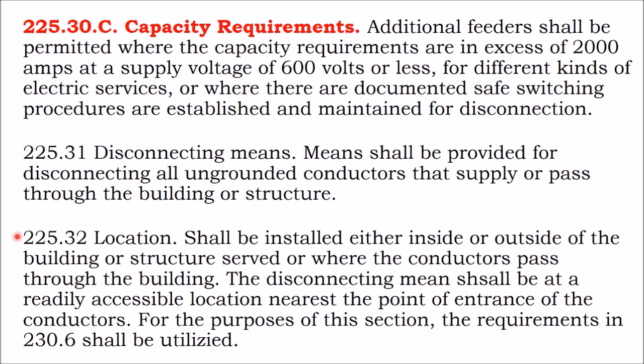Okay. Well, so now it comes time to service the inverter, and you want to turn the wires off inside the inverter, except they're hardwired to your array up at the top of the roof. And so while you might have a disconnect in the inverter that would be code compliant, it doesn't do you all that much good unless you can access the non-disconnected section.